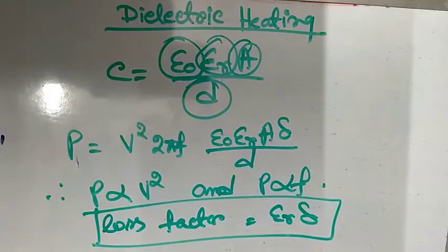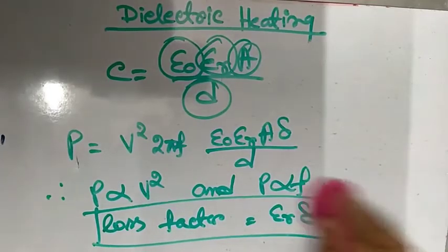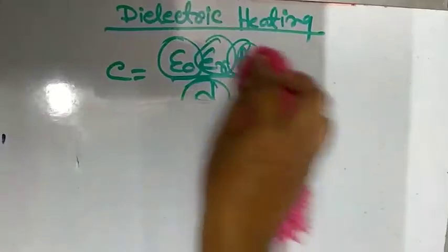Another reason why certain frequencies are better suited for a workpiece of a given dimension is the formation of standing waves. Now, if the distance between electrodes equals quarter or half wavelength at a given frequency, standing waves would be set up along the electrodes. Let me draw the picture so you can understand better.